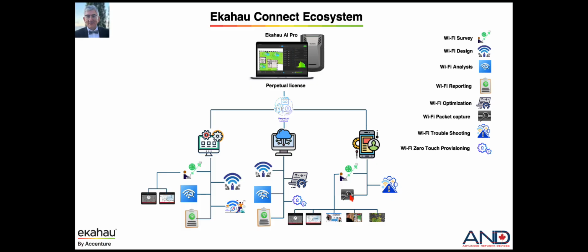Now, on the survey side, in comparison to the workstation, not only we can perform the stop and go and continuous surveys, but also can utilize the front and the back camera, the accelerometer, and the gyro of the mobile device and conduct what we call autopilot surveys. That makes the speed and accuracy of a survey increase in comparison to doing continuous or stop and go surveys.